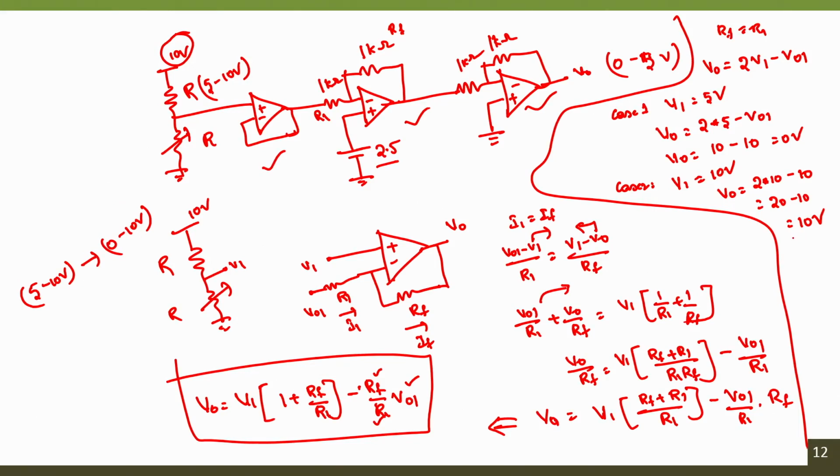But using a single operational amplifier, connecting the V1 output directly to the input of the non-inverting amplifier, we can avoid the use of the voltage follower configuration. And if this 0 to 10 volts is good enough, we can simply use a single operational amplifier to solve the problem, right. So, this is another approach of how we can solve this. Next, is this the only way?